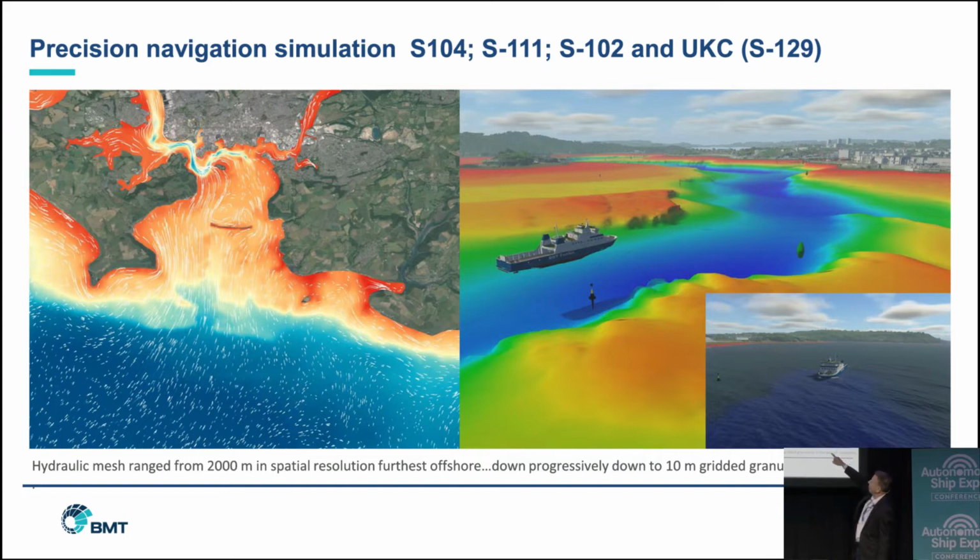And here we've got an autonomous ferry that we'd already modelled, actually coming into Plymouth. The water's removed here, so you can see the bathymetry model, the S102 bathymetry. But effectively, the hydraulic model is developing the S104 dynamic water height data, the S111 surface current data, and it's actually monitoring under keel clearance. So all that data has been taken on board by REMBRANT, fused, processed, and displayed.